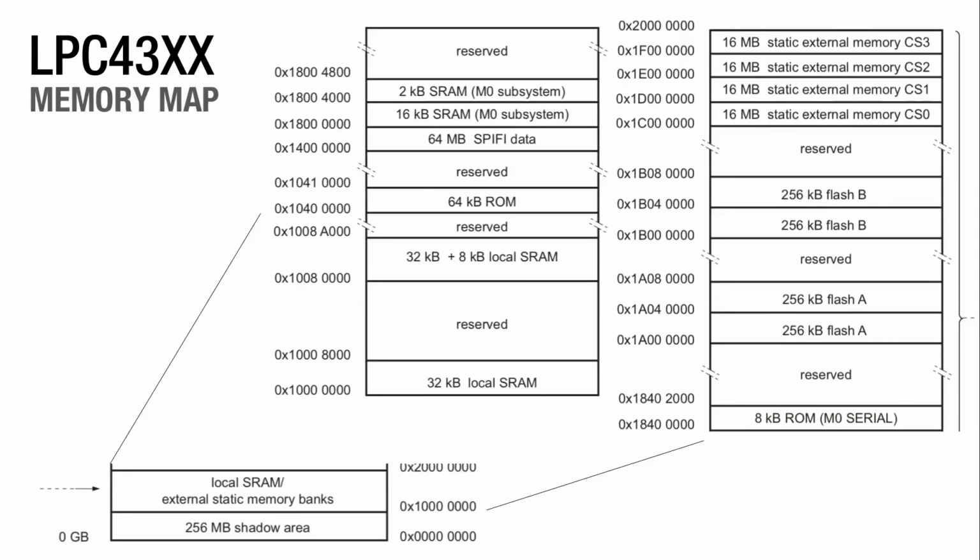There's only one ROM section here, which I can't laser point to. So this device has a USB bootloader that does all the same things as that tablet because it's compliant to the USB standard. So it can do things like respond to a get device descriptor request. And so we started applying the same kind of glitching attacks to the ROM.